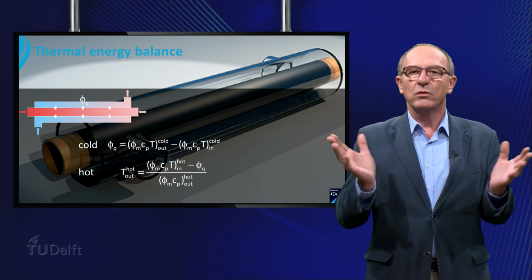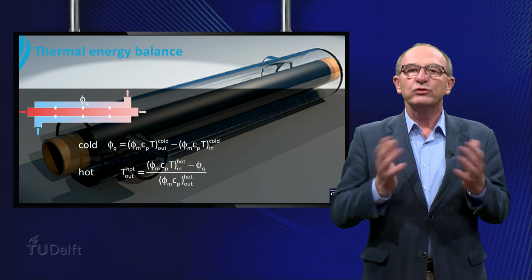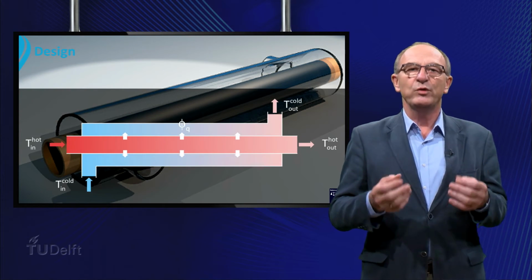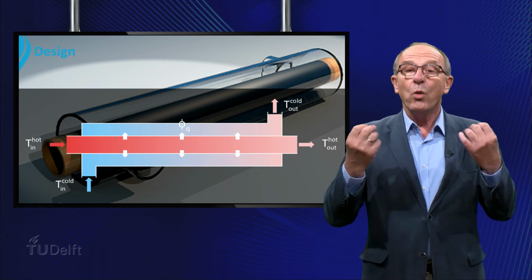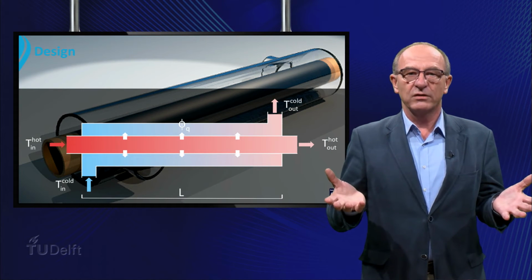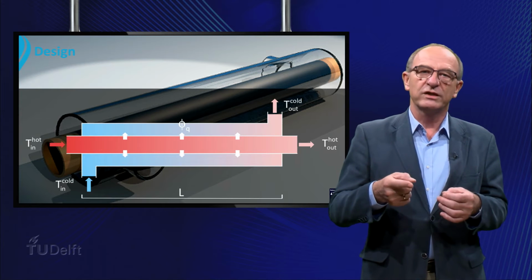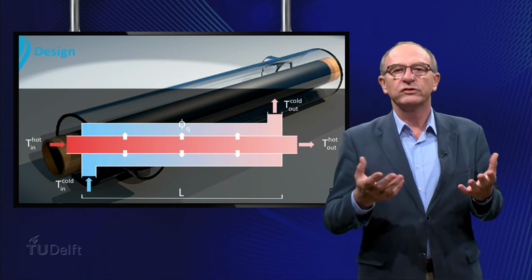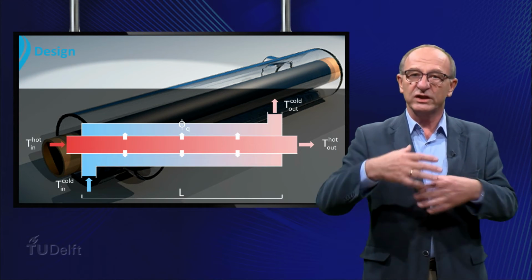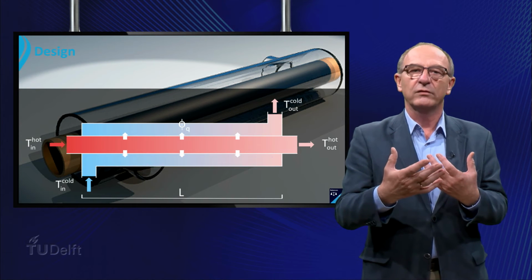Okay, we know all the temperatures, but to design a basic heat exchanger we want to answer a question like, what's the length of the heat exchanger? To answer this question, we need to know how large the surface area is over which the heat is exchanged between the hot and the cold fluid.